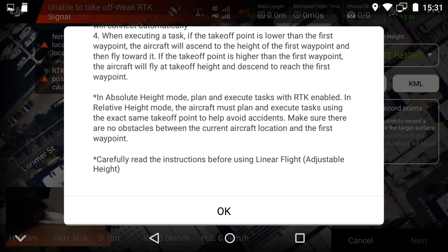Once you've saved everything and set the actual target surface height, you'll press Invoke on the drone and it'll return to the starting point. This will allow for the drone to continuously capture at an equal GSD above the power line or whatever you're going to be capturing.